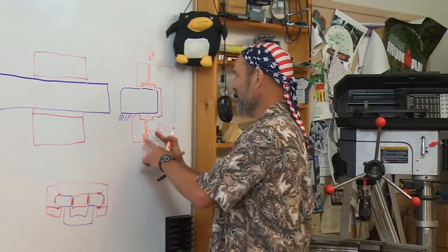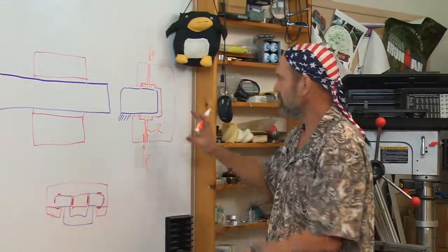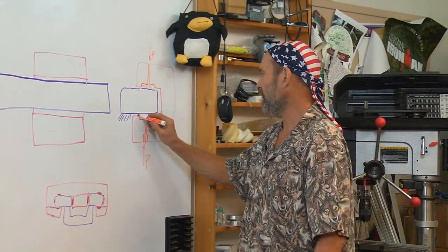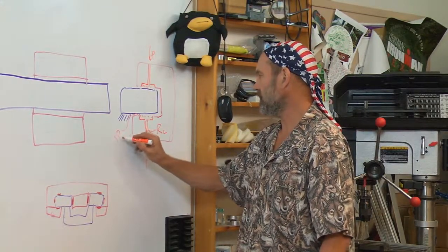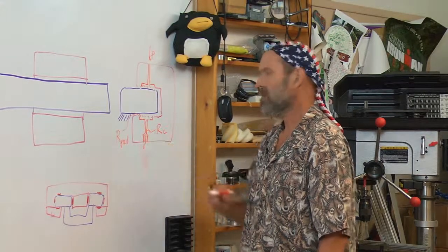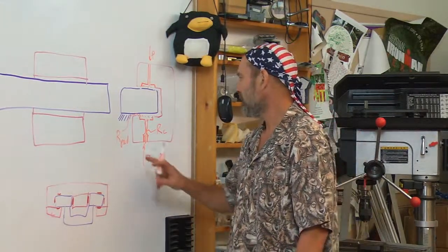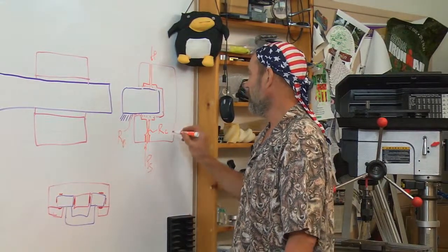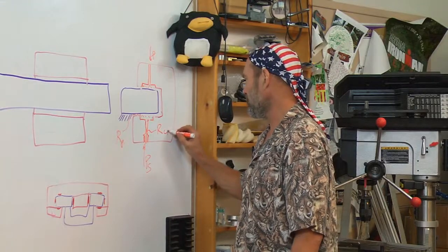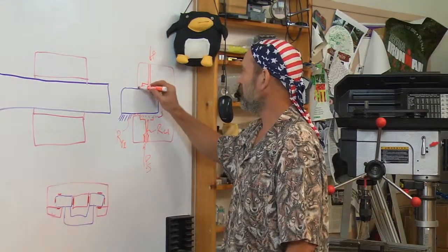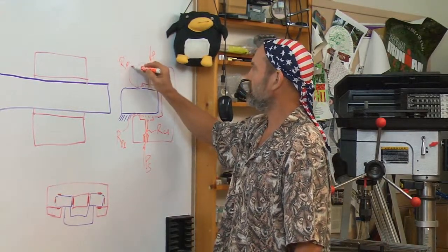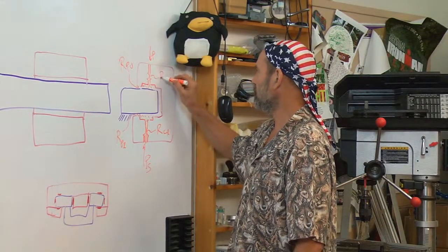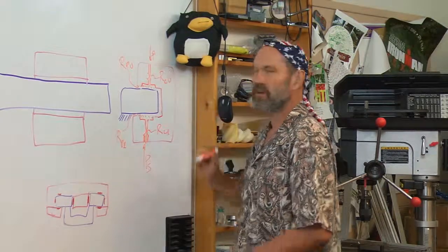This is called the compensation unit, or how you compensate the bearing. This flow out we'll call the resistance of the pad, or the pocket. We'll use pocket. We just call it RP, RC, and then pressure of the source. And this one will be, let's say, for the lower part. And then here, the resistance pressure for the upper part. And this is the resistance, this compensator for the upper part.